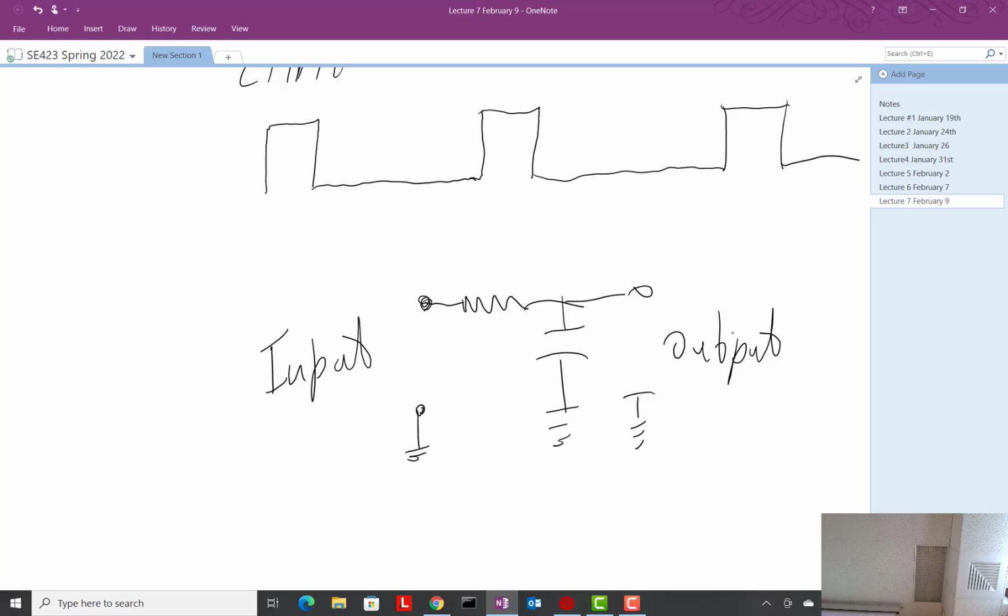You could do that. That's just a simple transfer function of A over S plus A, and you could play with this A right there and bring in a step response, bring in a square wave, and see that it comes out DC if you pick the right things. So in other words, the carrier frequency that you choose is dependent on the system you're driving. We're going to find with our motors what works really nice is 20 kilohertz.